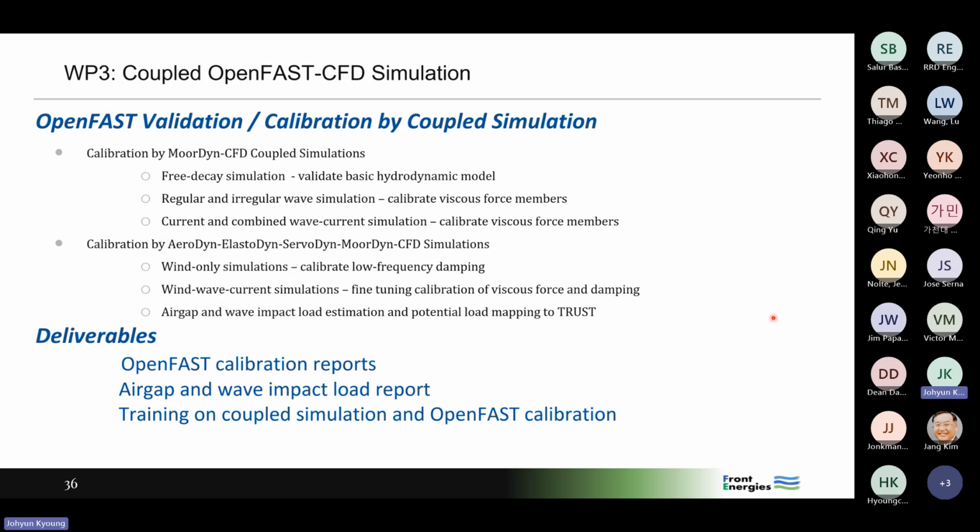Actually, FE wave was originally developed as a glue code for some nonlinear wave models and mooring tools like MoorDyn. But later it focused on working with Star-CCM+. Basically we use either an open source or commercial CFD solver. This is more of an interface, but it includes the fully nonlinear wave model, which generates both regular and irregular fully nonlinear waves that can be used as input for the CFD.